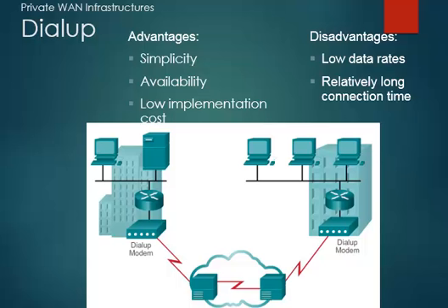Traditional telephony uses a copper cable for the local loop to connect the telephone handset in the subscriber premises to the CO. The signal on the local loop during a call is a continuously varying electronic signal that is a translation of the subscriber's voice into an analog signal. Traditional local loops can transport binary computer data through the voice telephone network using a modem. The modem modulates the binary data into an analog signal at the source and demodulates the analog signal to binary data at the destination.